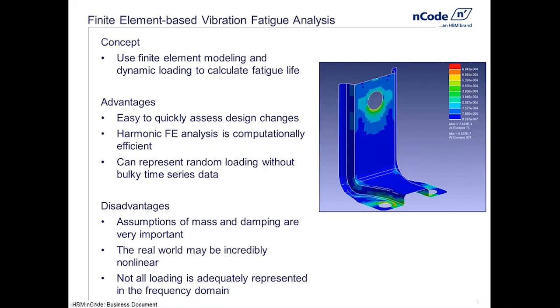As a matter of fact, small changes in stress result in very large changes in fatigue life. So we have to be sensitive to the damping input as a very critical input into getting fidelity of our fatigue results. Second disadvantage is we have to be careful of nonlinearity.